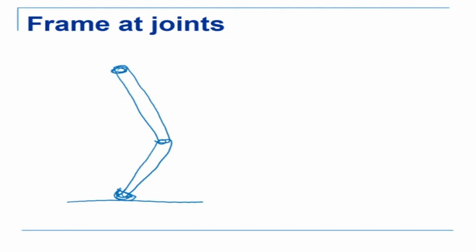Now let's move forward and look at frames at joints. Now we have seen that we define each leg. So this is my leg, and there is contact here. Now the first question that comes out is how many degrees of freedom. If we say it is 2 degrees of freedom, then the 2 degrees of freedom will be one revolute joint here, one revolute joint here. So it's a 2 DOF, the simplest. You cannot have one DOF, so it will have 2 DOF for each leg.